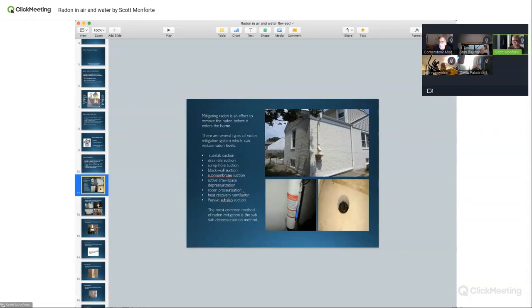When I see the cracks with all the efflorescence, I see the rusted columns, I see staining everywhere. Like this house yesterday, there was a water problem. And I told him, we'll put the system in, but you need to address the water problem. Now, his gutter downspouts are dumping. There are things that we can do outside. We talk to people that can certainly help reduce the amount of seepage, window wells, everything that we recommend as a home inspector.